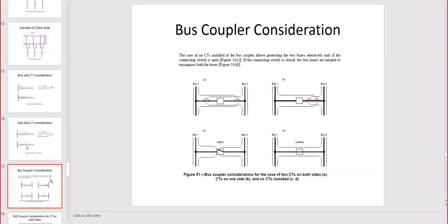Now what's happening if I have a breaker fault? Just to finish, I will not rely on the breaker. I will order the breaker to open, but whatever the breaker does, we don't know. So we will be forced to trip all the breakers in the zone. So this is a bus coupler. This is actually a switch. The same idea on the bottom.